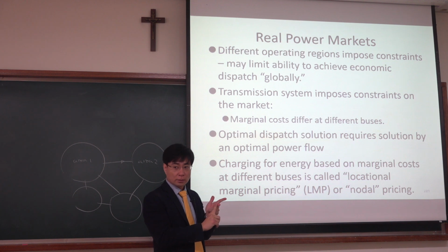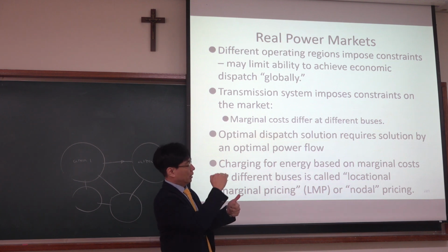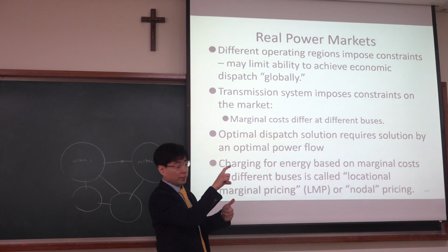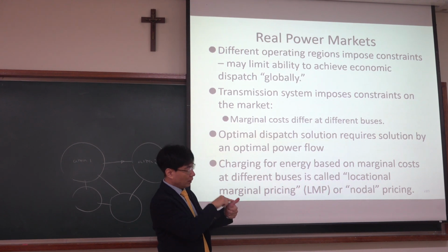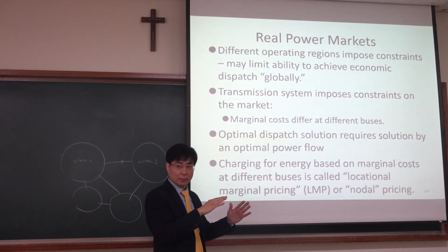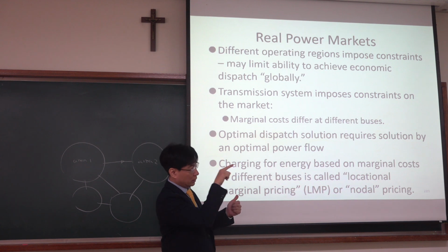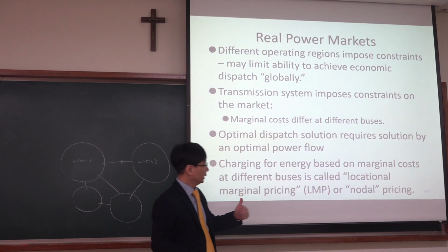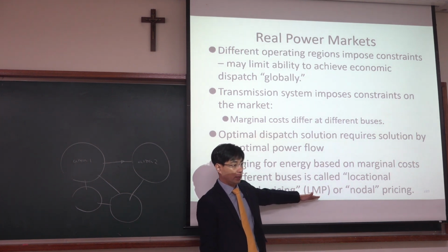So you may think, hey, for this generator, it has lower or upper generation limits, and there is a dual variable for the constraints. So maybe that is the same as LMP? No. We also need to consider the transmission line limits and power losses to exactly compute LMP.